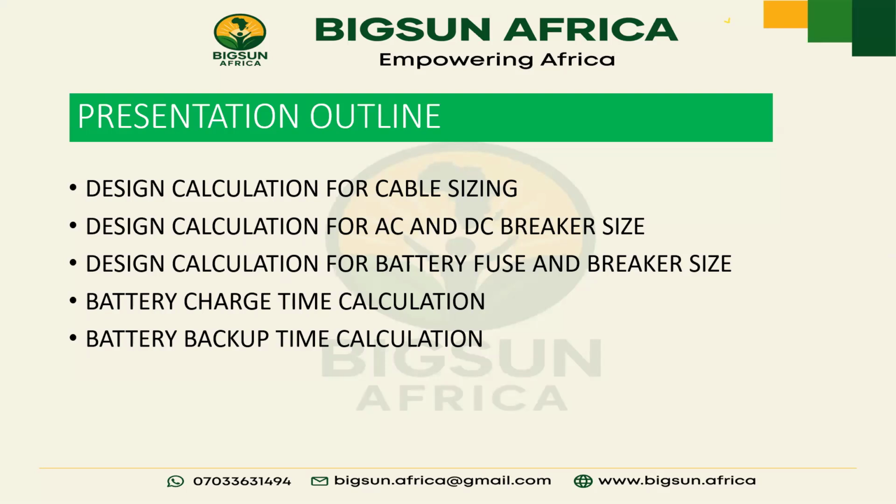Charge controller does not produce light. It's a DC-DC converter. The only time that charge controller can produce light for you is if it is a DC load you are putting on it. Maybe you have a DC fridge, which is very rare, or a DC bulb, which is common in some cases, or maybe any other DC load. But charge controllers don't give out AC current.